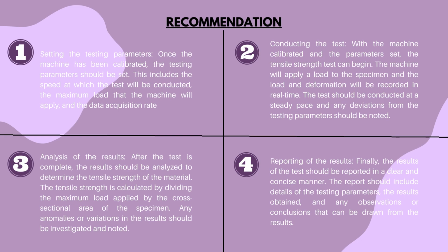With the machine calibrated and the parameters set, the tensile strength test can begin. The machine will apply a load to the specimen and the deformation will be recorded in real time. The test should be conducted at a steady pace and any deviation from the testing parameters should be noted.